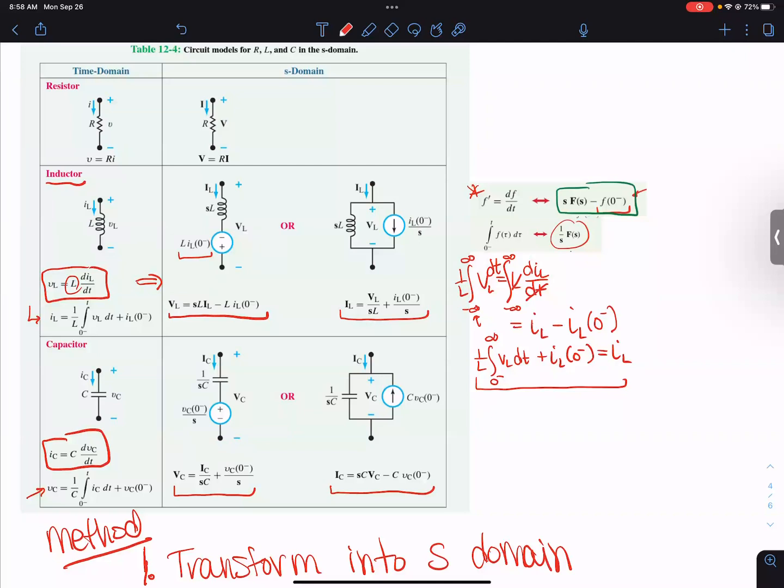I don't want to solve a 5th order differential equation. That's why we're doing this: now we can have an unlimited number of capacitors or inductors in there. Each one is going to contribute an S in the form that it goes, so if we have 5 in there, we're going to have a 5th order differential equation to solve, which is not going to be fun to do in the time domain. So that's why we are using this method, because we can solve any circuit this way, model it by these elements we know, and treat it like an impedance, which is just going to be so much easier. That makes sense?